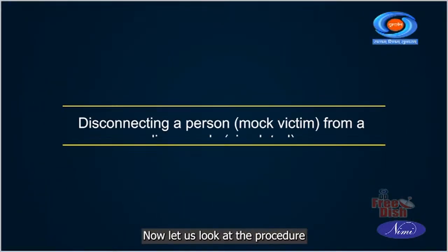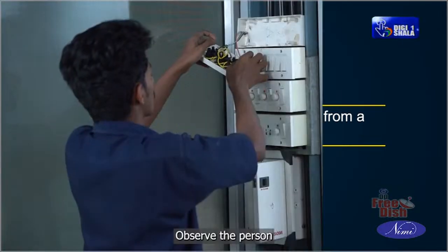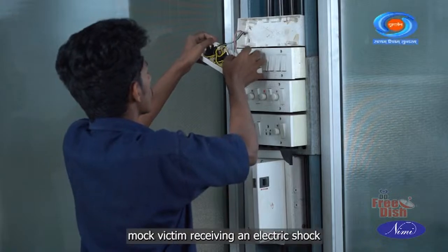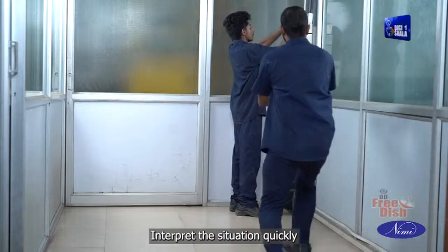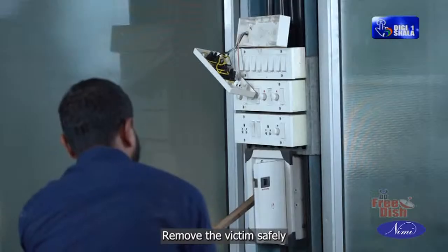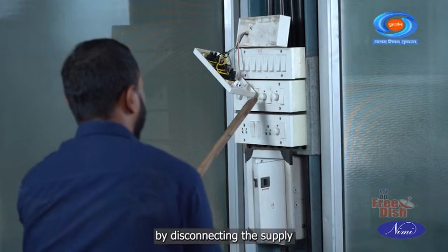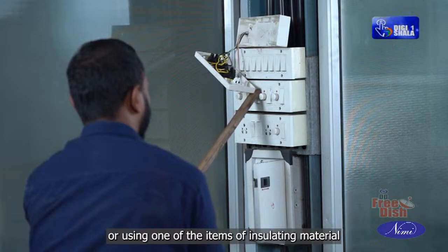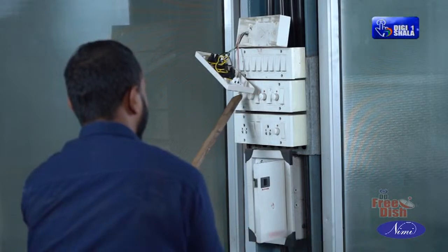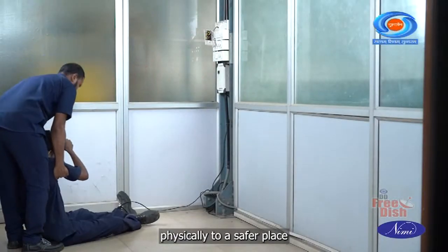Now let us look at the procedure for disconnecting a person from a live supply. Observe the person, mock victim, receiving an electric shock. Interpret the situation quickly. Remove the victim safely from the live equipment by disconnecting the supply or using one of the items of insulating material. Move the victim physically to a safer place.